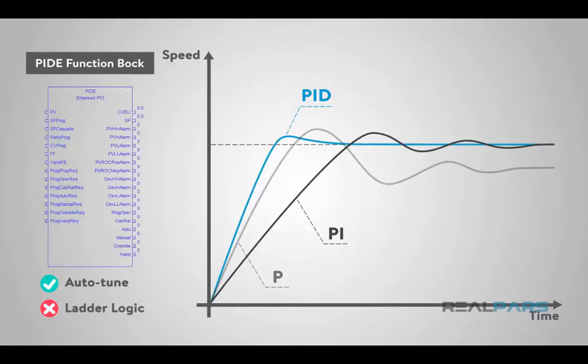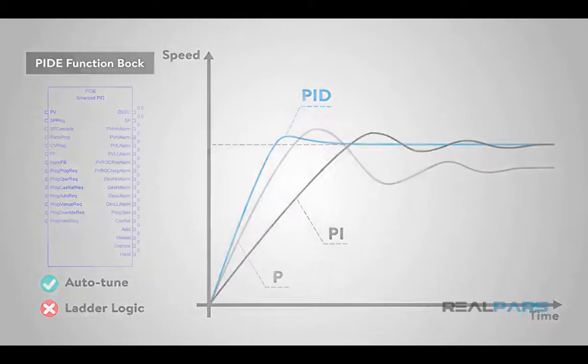This is especially useful for adaptive gains or multi-loop and cascade process control. The PIDE instruction can be switched between program and operator modes and provides full bumpless transfer into and out of cascade mode, and this instruction has more fault handling selections. The following programming steps assume the reviewer has Studio 5000 experience.